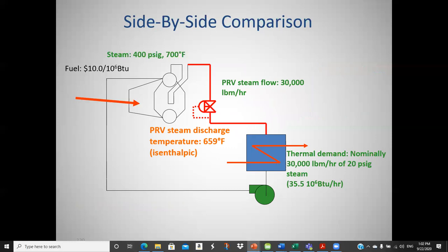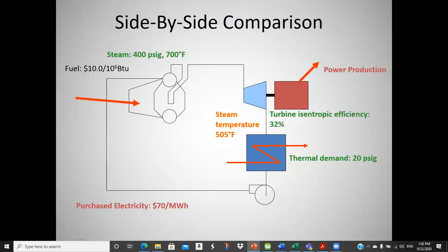All the energy in equals all the energy out. What about here? Is that steam turbine taking some energy out of that steam flow? Darn right it is, and it's converting it into shaft power, which is turning that generator, which means I get 505 degrees Fahrenheit. Is that likely to change my steam demand?